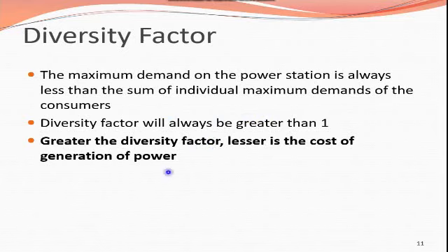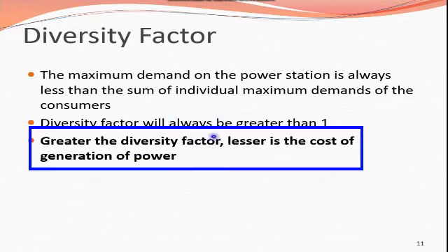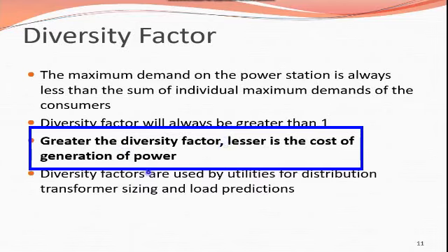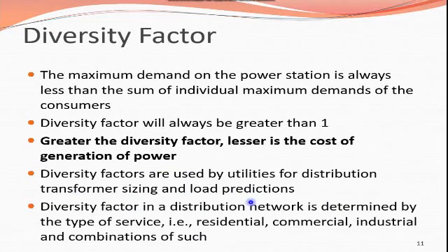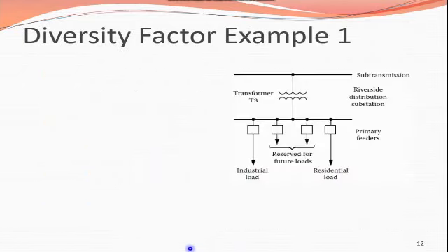Now here is an important point. The greater the diversity factor, the lesser is the cost of generation of power. Diversity factors are used by utilities for distribution transformer sizing and load predictions. Diversity factor in a distribution network is determined by the type of service: residential, commercial, industrial and combinations of such.